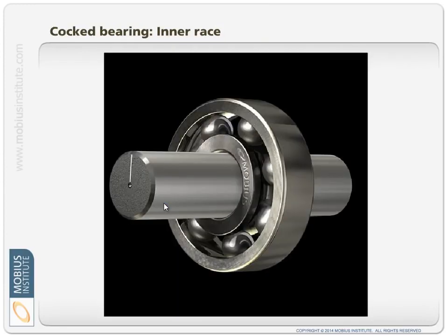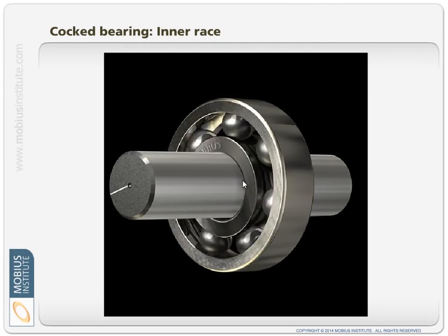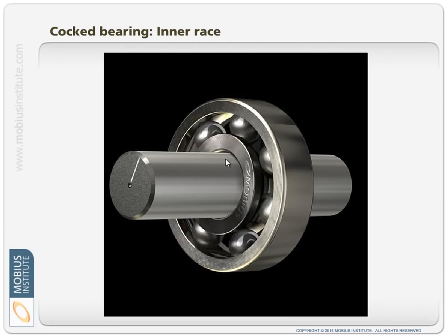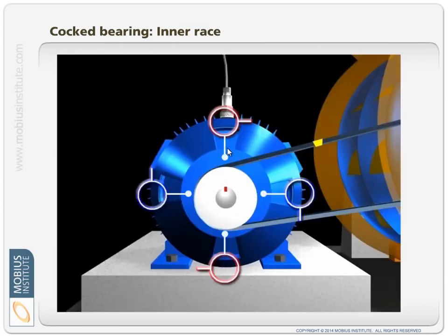And oh look, we've got the bearing isn't mounted correctly on the shaft. It's rocking and rolling every time the shaft turns, which is damaging our bearings. But if we compare the phase from here to here to here to here, we see a 90 degrees phase shift because of that rocking motion. Now, yes, we wouldn't take a reading here because we've got belt. I need to come up with a better illustration, but anyway, that's what we've got.